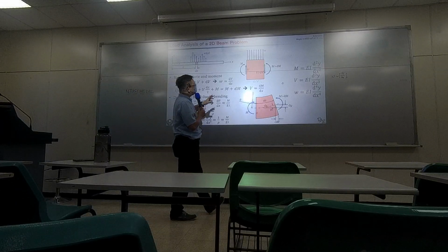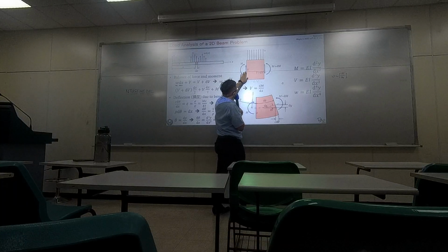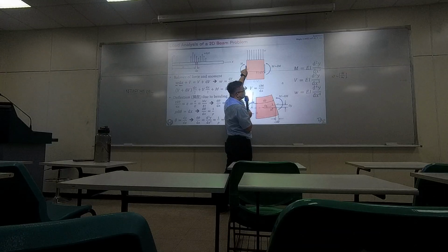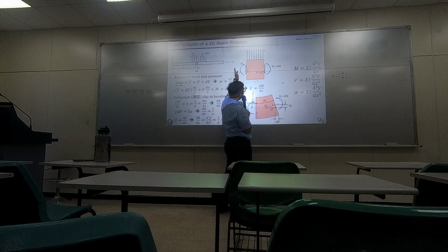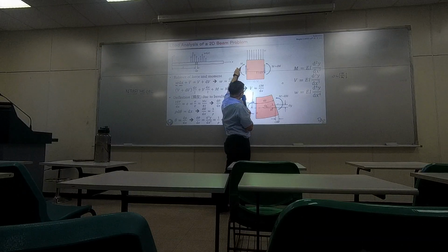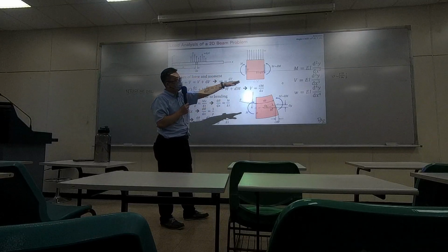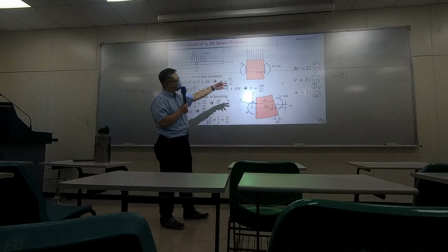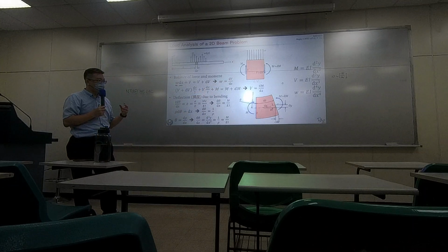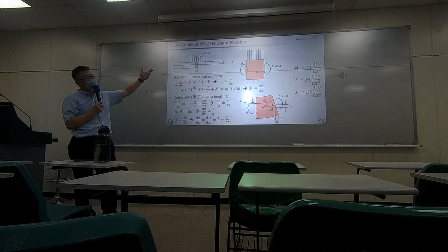So in this configuration, we assume that on the left-hand side there could be a shearing force V going up, and we have a moment going clockwise, M, on the left-hand side. On the opposite side of the material, there will be the same amount of shearing force and moment, representing a pair of the shear force and the moment.